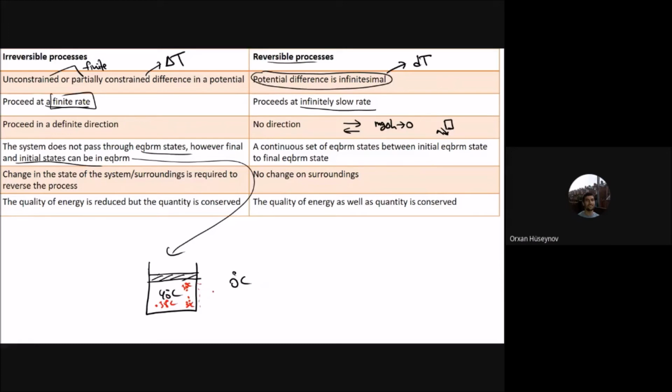The temperature doesn't have infinite conductivity, that is, it doesn't propagate into the domain with infinite speed. It has some finite speed. Therefore, the boundaries that are close to the 0 degrees Celsius surface follow its temperature much better than the points that are away from it. Therefore, inside the material you have a gradient. Here you have higher temperature, and here you have lower temperature, and therefore it is not in equilibrium.